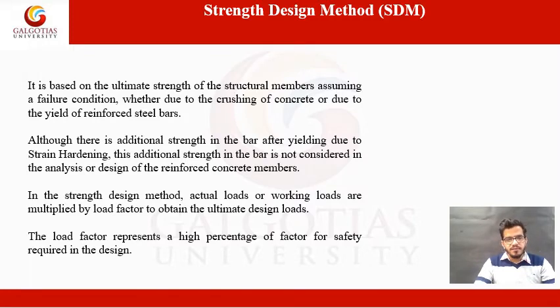In the strength design method, actual loads or working loads are multiplied by the load factor to obtain the ultimate design loads through different types of codes. The load factor represents the high percentage of the factor for safety requirement in the design.